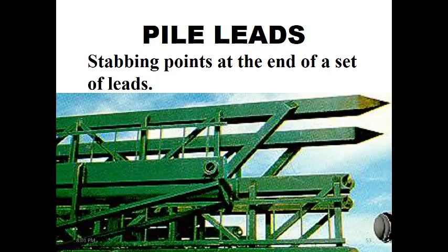In order to position it properly, we have to put these lids, which will have these sharp stabbing points, to immerse it into the top layer of the soil to position itself properly. Then put the pile over it so it will be really stable and wouldn't change the angle while you are nailing down the pile.